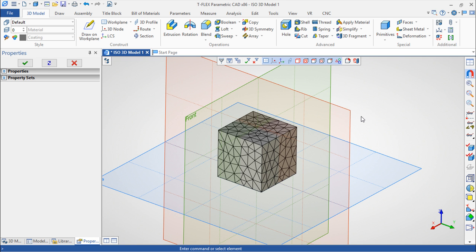And these real characteristics are going to be used for the studies. The characteristics of the material can be divided into groups. We have what we can call the first type or the first group, which basically affect the display of the 3D objects inside the graphical area. And we have a second group or a second type of characteristics called physical parameters. Things like the density, the elasticity modulus, strength limiting tension, and others. These are the characteristics that are needed to carry out the calculations.